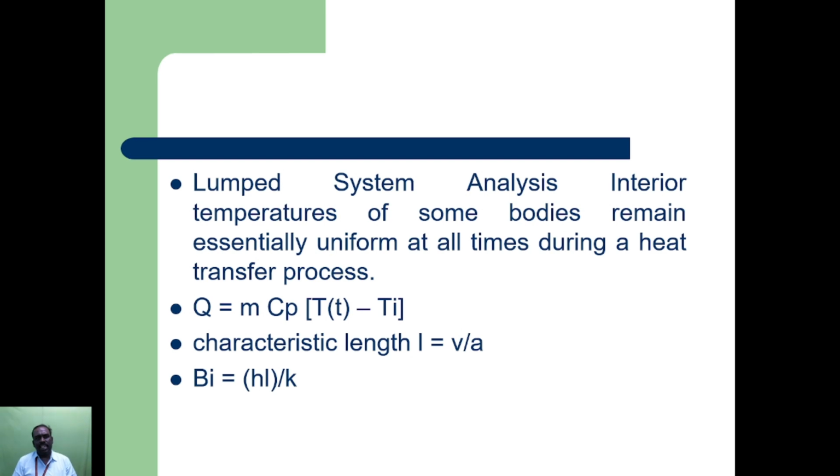In this transient state conduction, we are going to discuss lumped system analysis. Steady state we have not discussed here; we only study transient states. First, lumped system analysis. What does lump mean? Total, completely, in a particular system. The interior temperature of the body remains essentially uniform at all times during the heat transfer process.